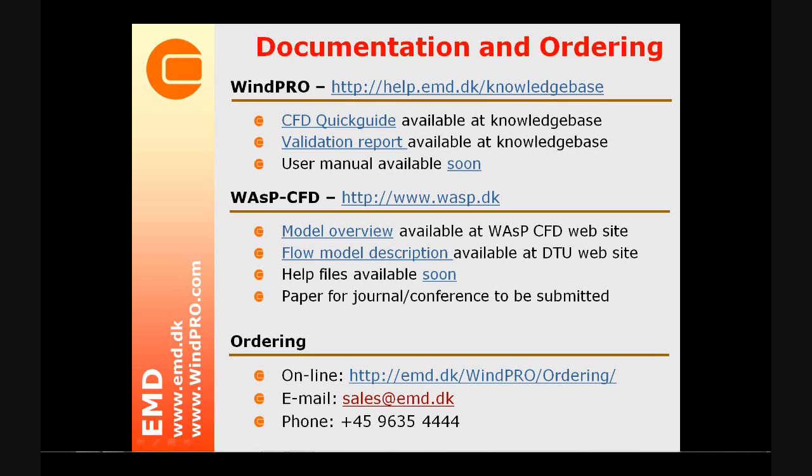So I have two related questions here that I'll try to answer in one go. So the question is, if profile fit is not a good performance indicator, which indicator is then better? And you say, if we have measurements close to hub height, a very good performance indicator, you could say, indicates how will you perform on the errors which are most important to your prediction, is how well can I predict between two masts which measure at or near hub height.